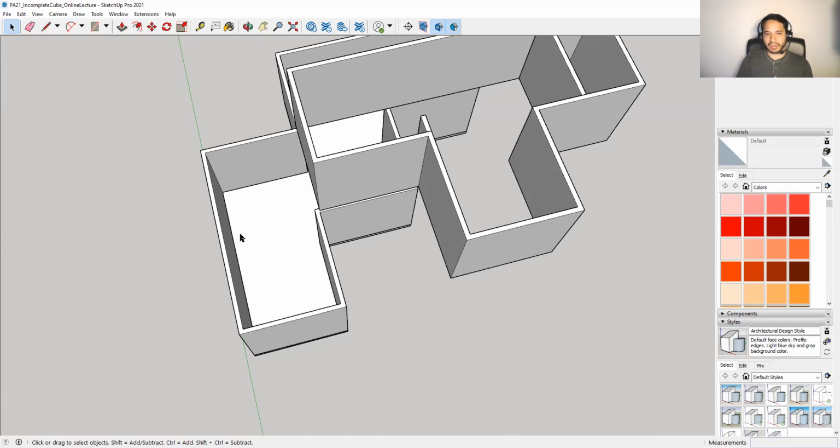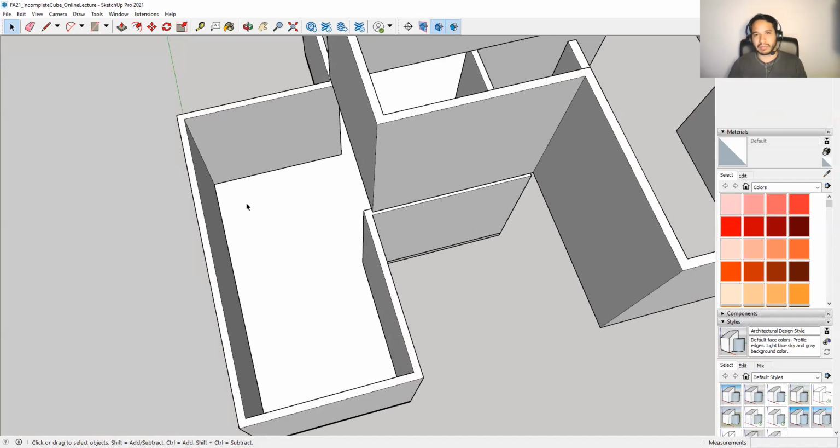So we're going to need a length, or the amount of steps that we're going to need, which I believe is going to be 20 steps. The amount of steps that we're going to need is going to take up 18 feet, 6 inches of linear footage. Okay. Now you can place your staircase wherever you want, but there is a general rule, and that general rule is that staircases are about a minimum of 3 feet wide. So everything we're going to be doing in regards to stairs is going to be a 3-foot wide staircase.